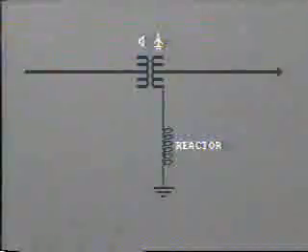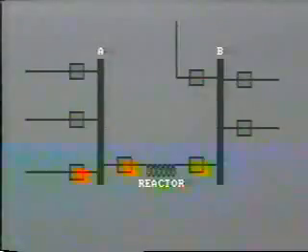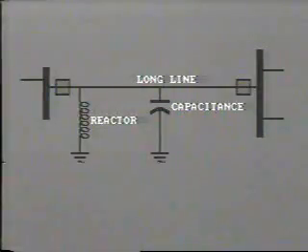Now at this point, let's extend our overall view of transformer protection to include reactors. This is because there are many similarities in construction, and therefore protection is also similar. Generally, reactors are air-cooled or oil-immersed single or three-phase windings on an iron core. Where is the reactor installed? Well, typically in a grounded neutral to limit fault current, between buses to reduce magnitude of current flow, or shunt connected between line and ground to compensate for capacitance on long lines and prevent high voltage levels.